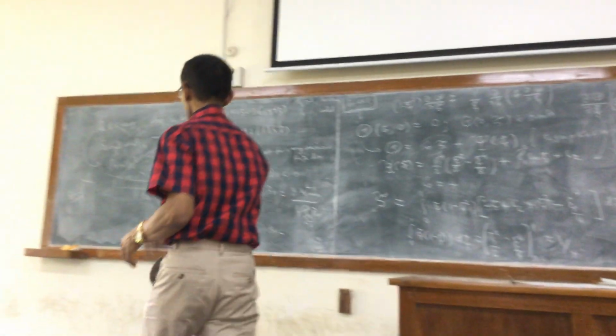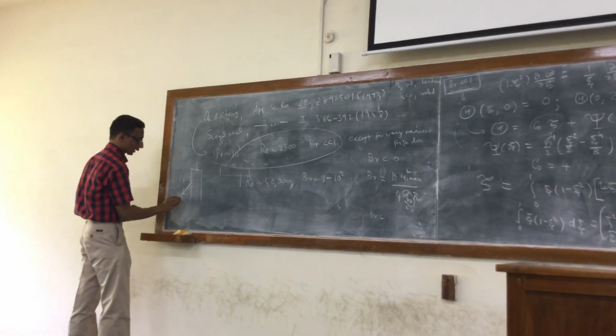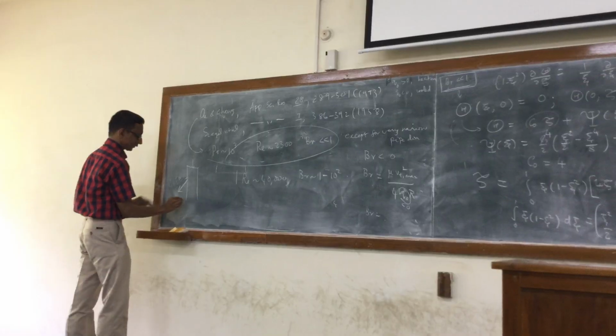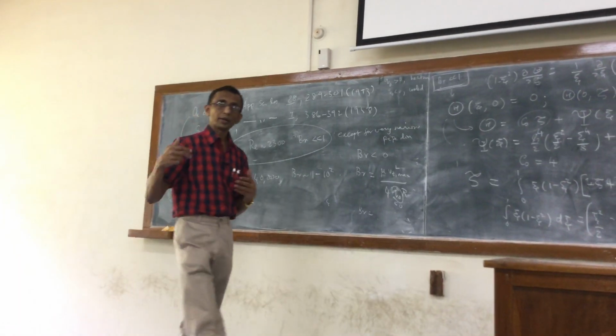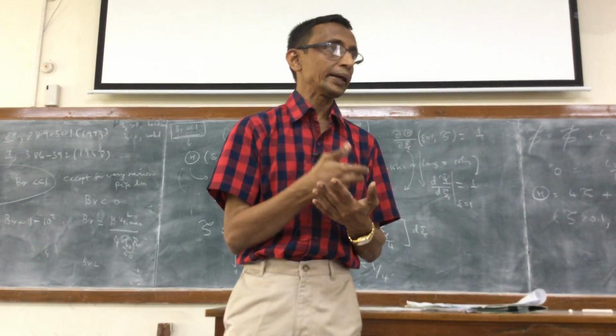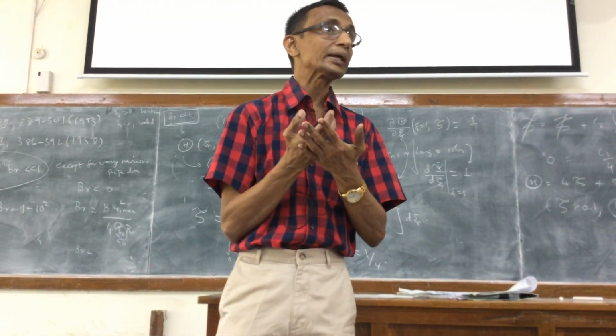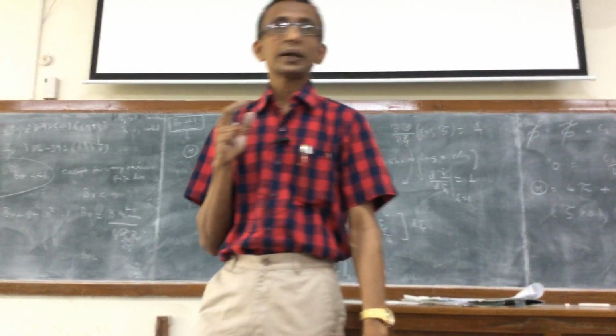However, if on the other hand you are considering the case of cooling a liquid, it means Q0 is less than 0, so the arrow here points to heat being removed. On the one hand, you are removing the heat in order to cool the fluid, but the viscous dissipation effect is going to increase the temperature, so one has to be careful.